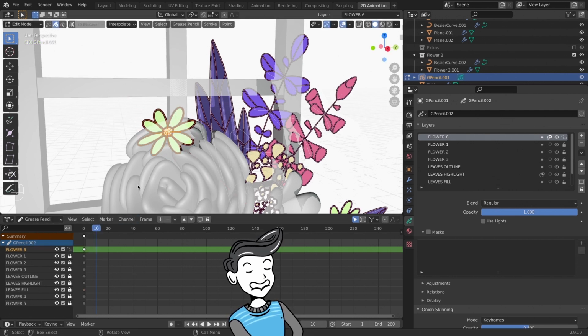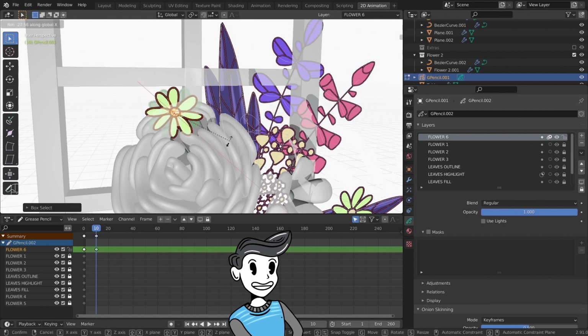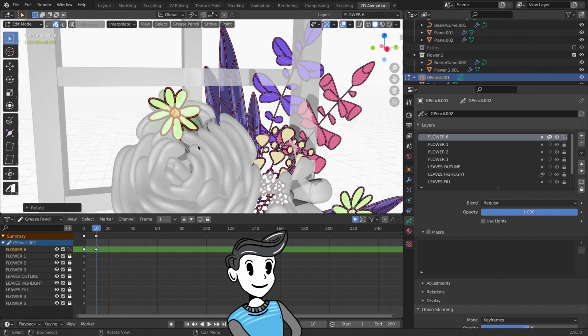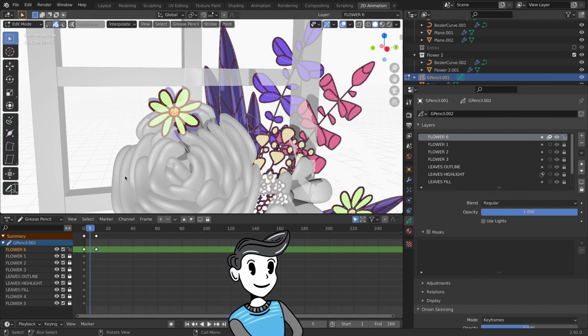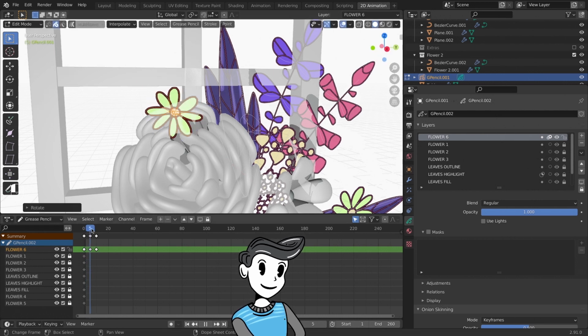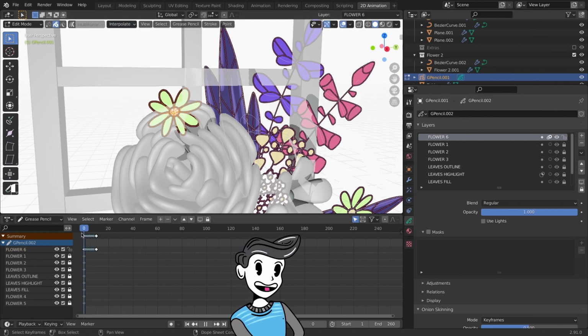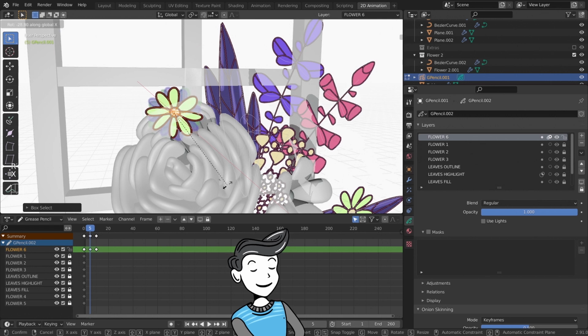Let's delete these keyframes. For this, I'm going to animate every 5 frames. So move the playhead to 10 and rotate the lines with R, then X, and choose how far you want it to rotate. Then click. Now, in between the 2 frames, I'm going to animate a frame to make a smoother transition, like this. Another way you can do this is with interpolation here at the top. However, I'm just going to animate manually for now.